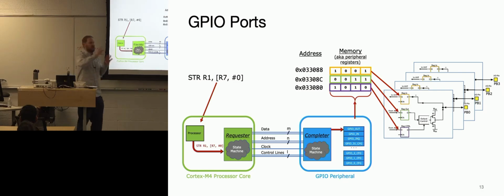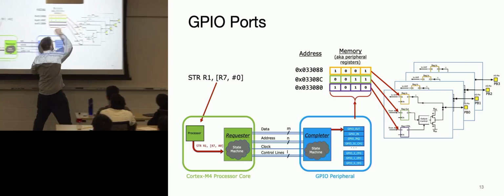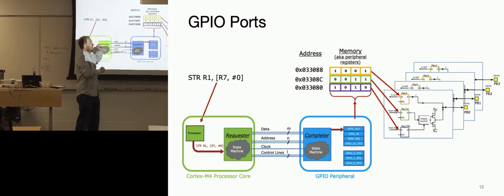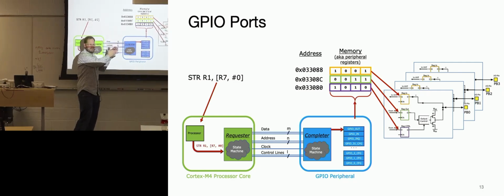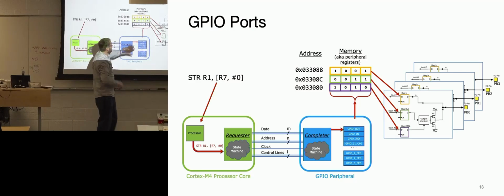Yeah. I had an animation at one point where we had all the different peripherals, all the memory blocks, and we distributed them throughout. So the core doesn't know that they're distributed, right? The core just thinks, okay, I have memory addresses 0 to F, whatever it is, 4 gigabytes I can write to. It just happens to be that some of those represent different things. Some of them will represent FRAM or SRAM, some will represent flash, some will represent these registers.